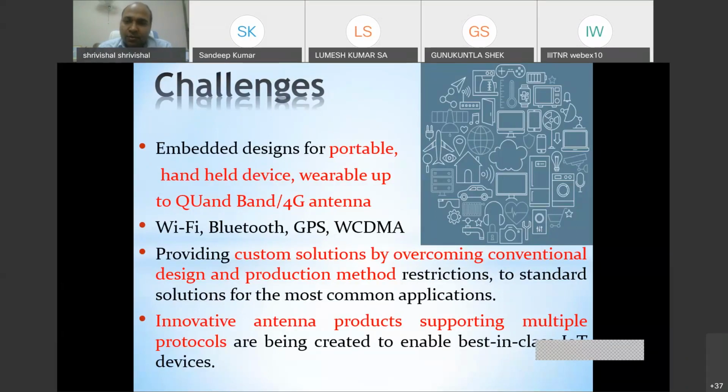The moment it is one platform, there is the multi-band phenomenon. People look for this from the same antenna system, whereas the space constraint is there. If you can design one antenna for one specific band, you will always get better performance. The moment you go for one antenna with a multi-band antenna system, there will always be some kind of trade-off in terms of characteristics as well as performance. If you compare all their parameters, you can find these differences very easily.